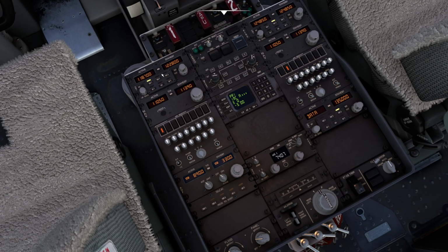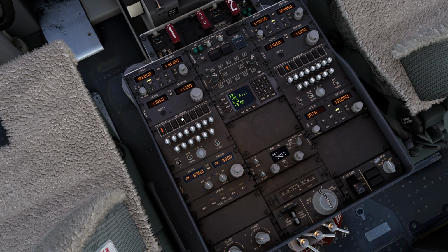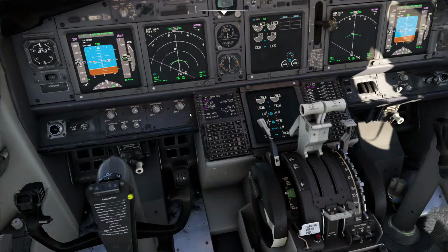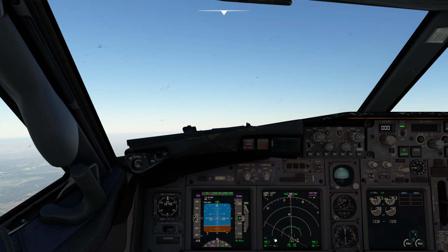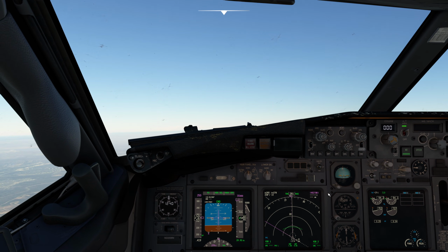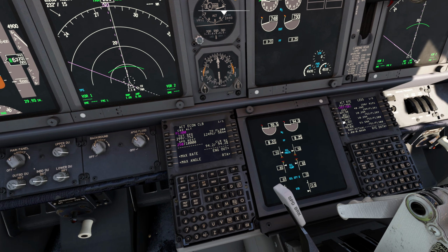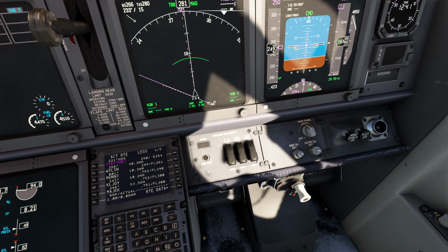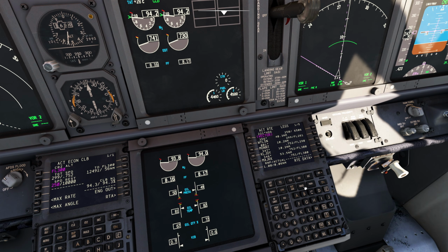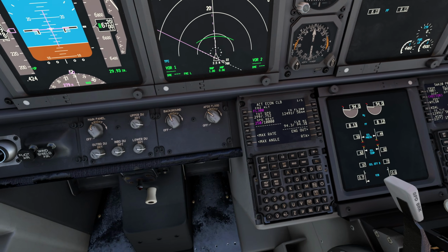Let's go ahead and switch over to Unicom. That's 122.8. And that's good for our radio calls unless ATC hops online. All right, we're going to continue that climb up. Let's go ahead and put in a direct to WESLYN. So the way you do that is, let's do it on this side. Do progress there. We'll talk about that in a minute.